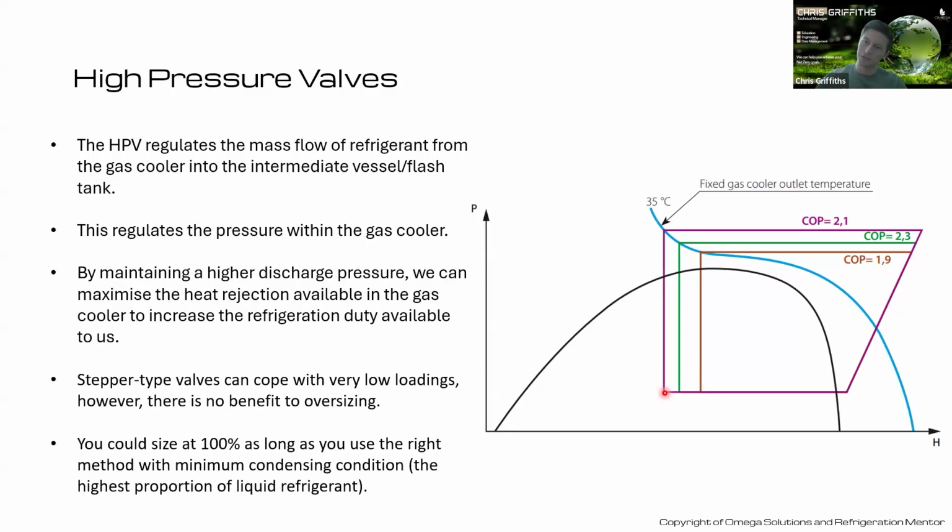So that is why we may want to artificially raise the discharge pressure in an ambient where traditionally you might get away with 75 bar. Actual temperature, etc., is a bit lower. But we're not making the best use of our system there either. Furthermore, if we had heat recovery, we're now getting even more heat recovered along the top. So again, it makes sense to do.